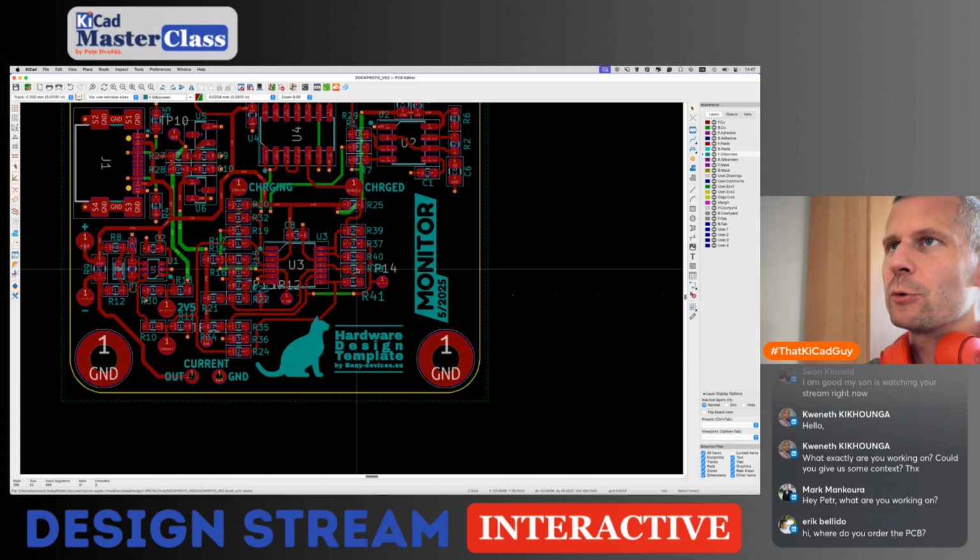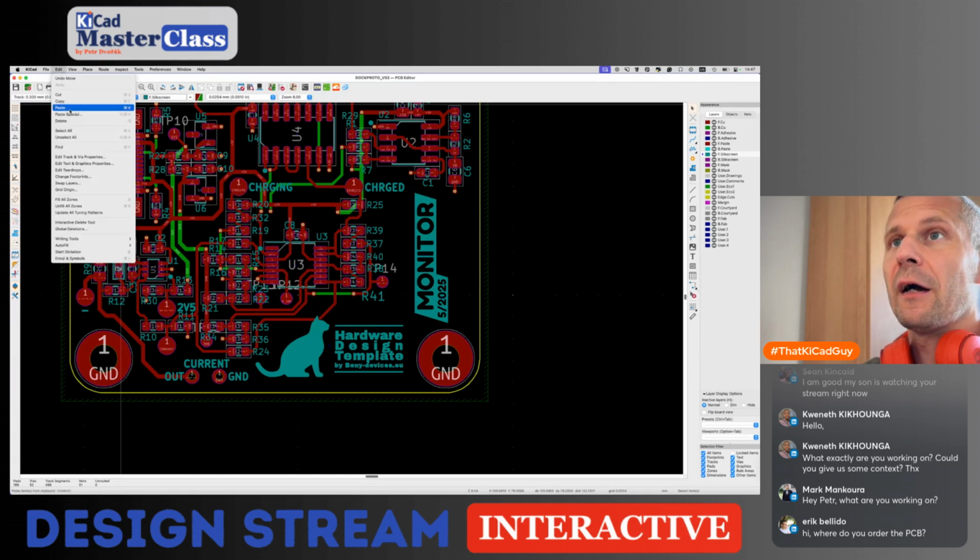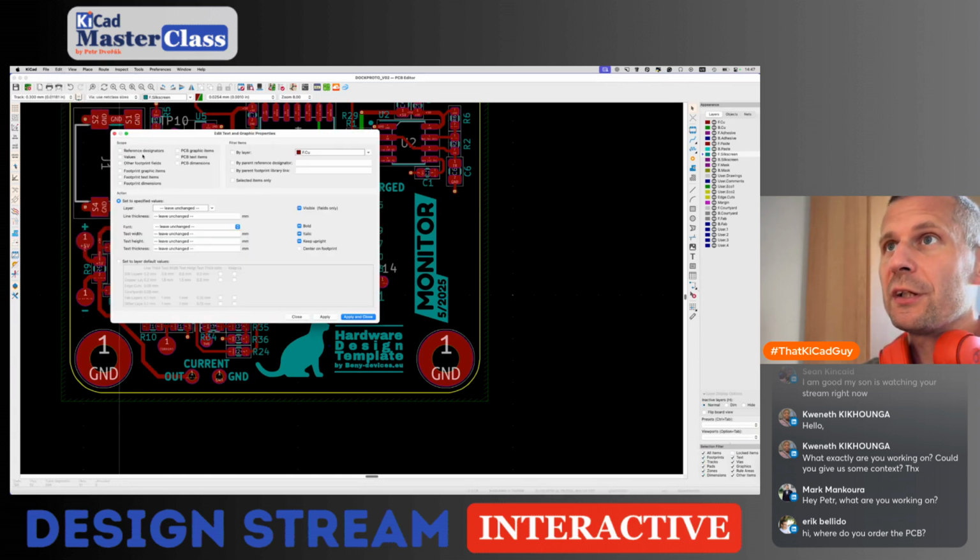reference designators to the same identical size, I use the edit text and graphics properties, and check the reference designators in layer silk screen. Layer will be unchanged and width will be 0.7 and height will be 0.7 with the thickness 0.1, I guess, and apply.